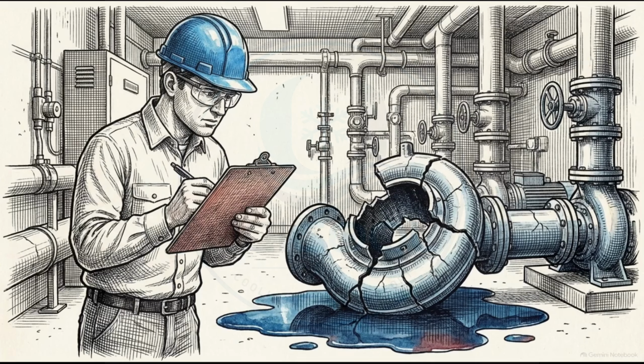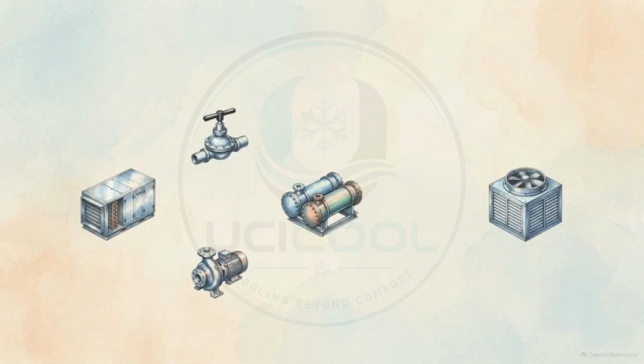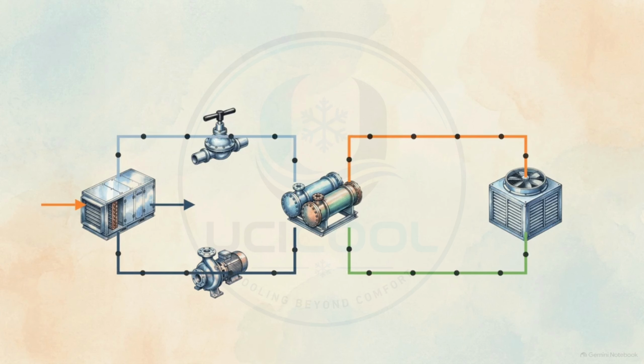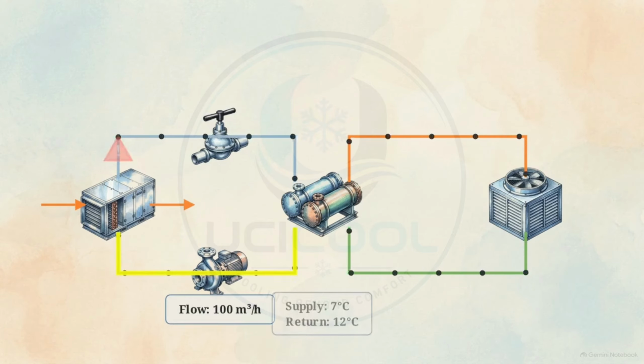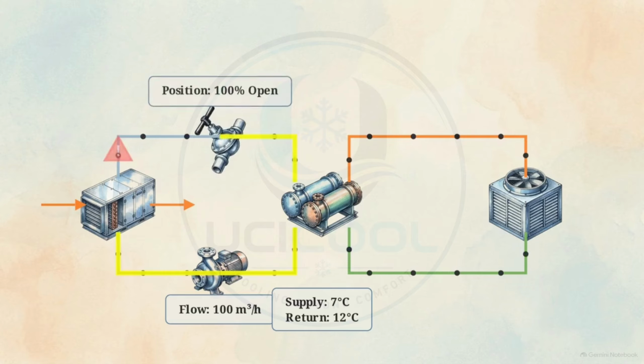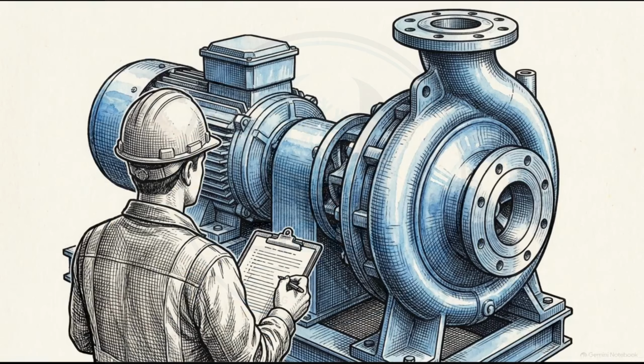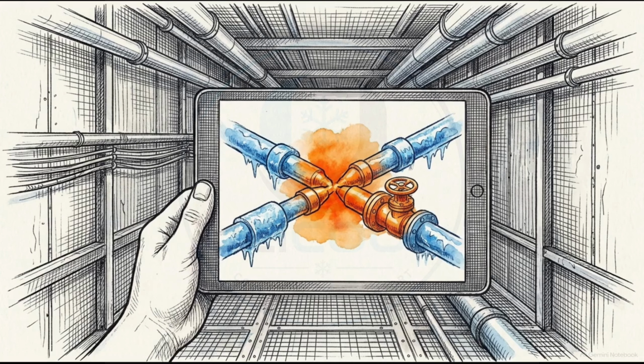Systemic fluid dynamic imbalances, or neglected resistance, frequently manifest as mechanical pump failures, which are often incorrectly attributed to manufacturing defects. To correctly manage this architecture, we have to view the entire water-cooled plant as an interconnected machine, integrating both the chilled water loop and the heat rejection side. If an air handling unit reports poor cooling performance, the diagnostic logic must follow the fluid. You verify pump flow, check supply and return temperatures across the chiller, inspect the physical coil condition, and confirm the valve positions. Simply blaming the pump for low cooling is an incomplete approach. Technicians must trace the entire thermodynamic and hydraulic chain to locate the restriction.